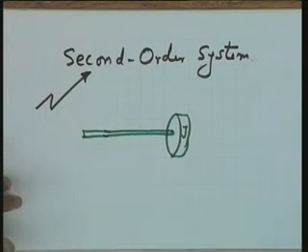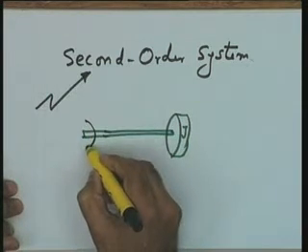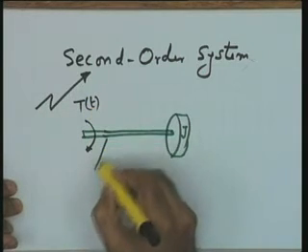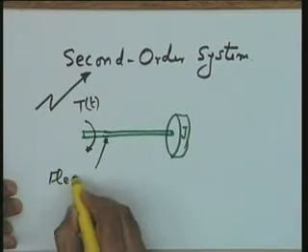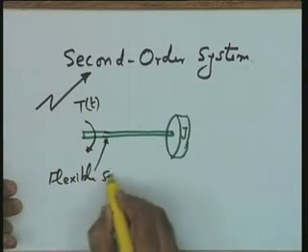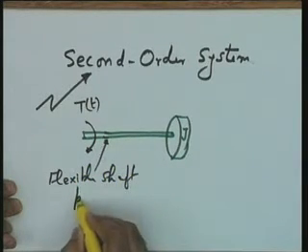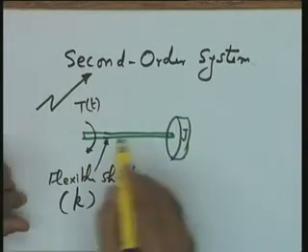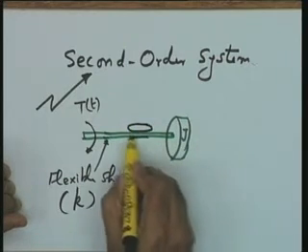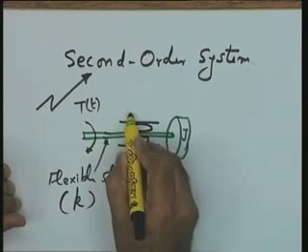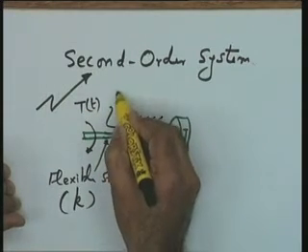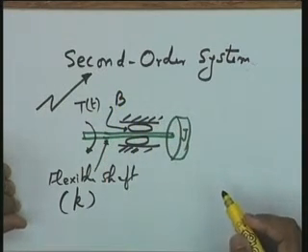In this particular case the shaft is flexible, the torque T is the input, let me make it a function of time, and let me write it here specifically that it is a flexible shaft, and let me take the spring constant for this, the parameter which describes this attribute of the shaft is K. As I did earlier, the frictional environment is schematically represented like this, and let me say that B is the viscous friction parameter.